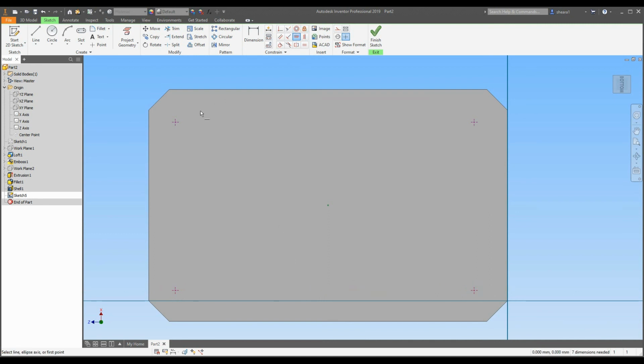I don't know if that actually got created or not. Now I'm going to do a horizontal constraint between these two, and they should be good to go. Let's see. So this has a vertical and a horizontal constraint. This just has a horizontal constraint, so my vertical one actually never went through. So here we go. Just going to vertical constrain those two. This guy's vertically constrained to this guy. This guy is vertically and horizontally constrained to this guy. This guy is vertically and horizontally constrained between these two. And this guy is vertically constrained between this guy.